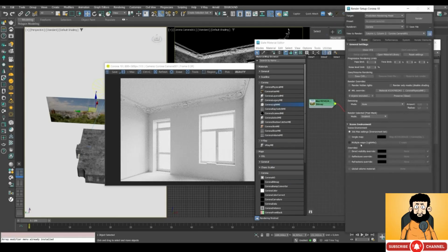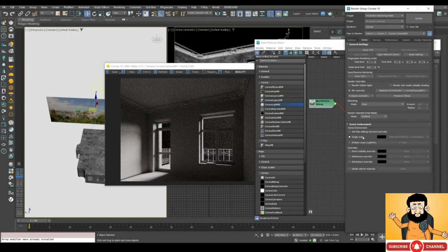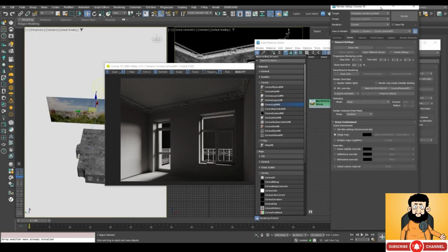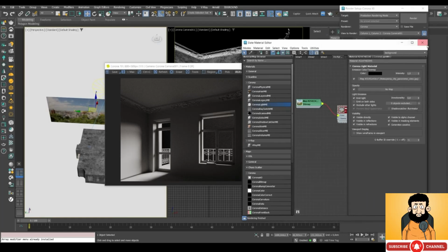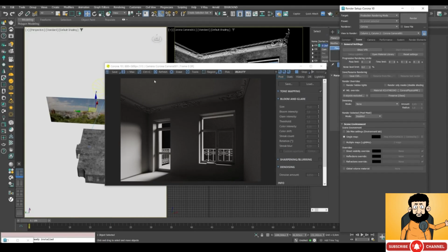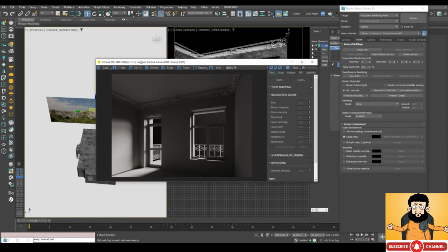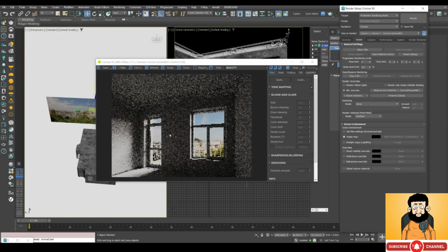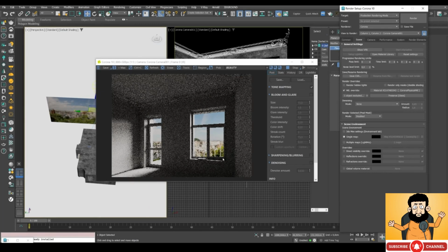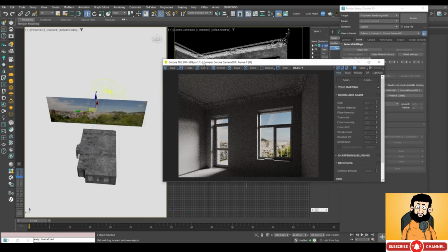We can actually go to render settings and turn off all the lights. See? And you can see that the scene is still illuminated, but we don't see any background yet. But that's because we need to exclude the background from the override option. We're using a clay material as the override material, and the background has turned gray too. So what we do is we simply select the background and click this plus icon to exclude it from the override option. And voila, the background is finally here.